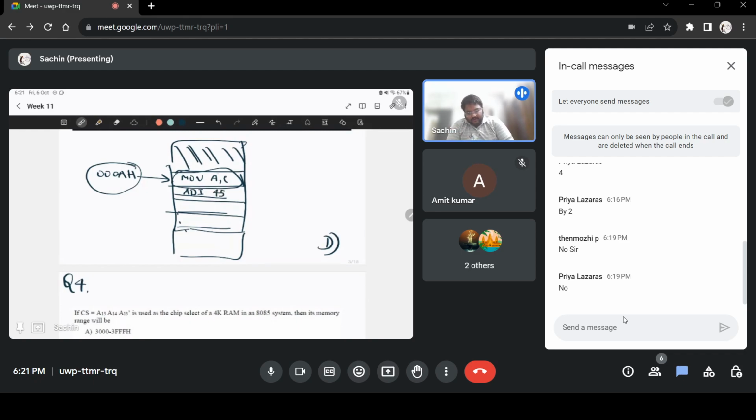So once it does the first instruction, this program counter, it will increment it by 1. It will go to 000B in hexadecimal, that is this, and then it will fetch the second instruction and execute it, and during that time it will increment it by 1, 000CH. There will be one instruction here, so it will keep track of at what part of your program you are.